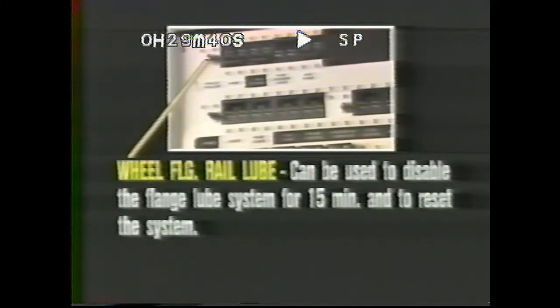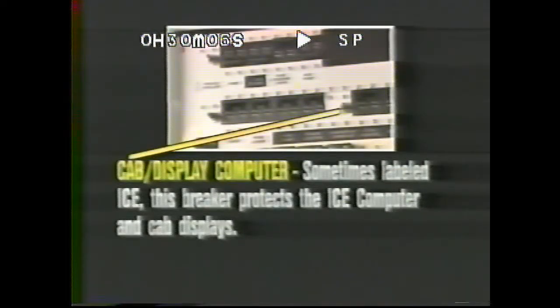Wheel flange rail lube can be used to disable the flange lube system for 15 minutes and to reset the system. ABICO, air brake in cutout, prevents dropping out of the air brake system computer due to low battery voltage when starting. This is a reset breaker only. Cab display computer, sometimes labeled ICE. This breaker protects the ICE computer and cab displays.